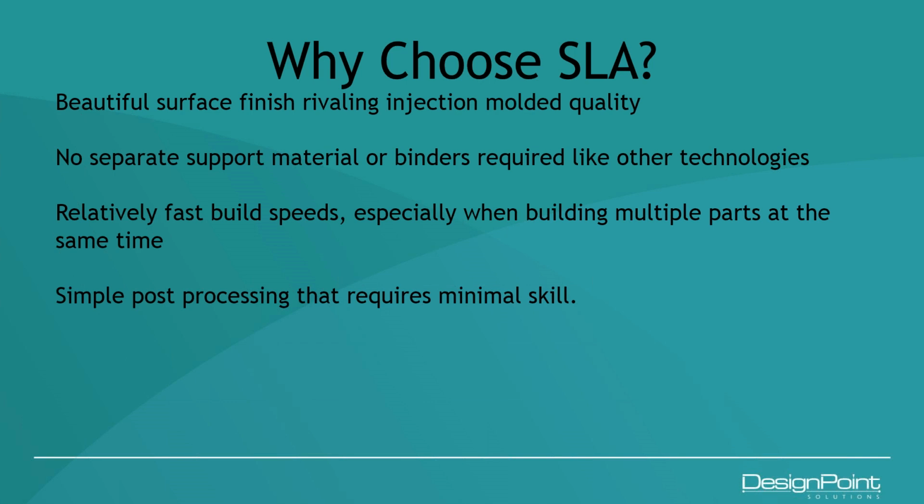My assumption here is that people are familiar enough with 3D printing technology. They understand what I mean when I say post-processing. If not, just understand that whenever you build a 3D printed part, some level of processing after it comes out of the printer is required. That may be removing support materials, that may be cleaning, that may be polishing. There are a few things left. I think over the next decade or more, we're going to see that get simpler and simpler and simpler. But where we are right now, there's still some level of support.